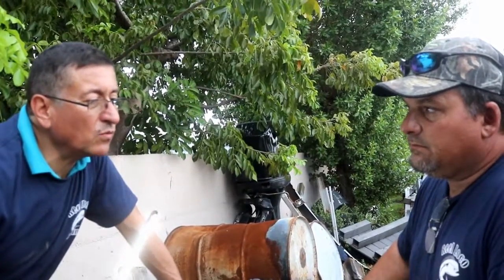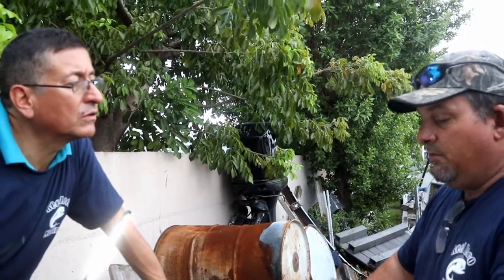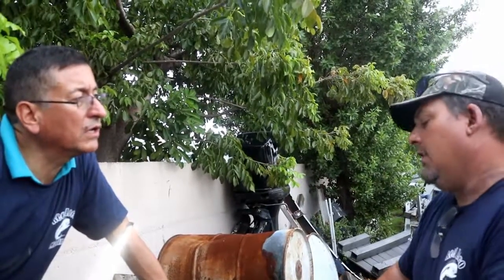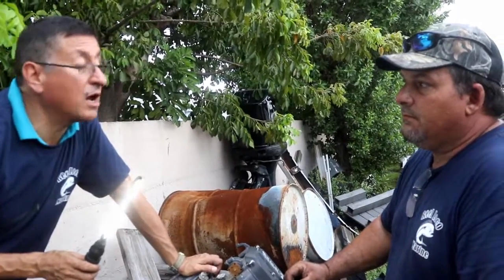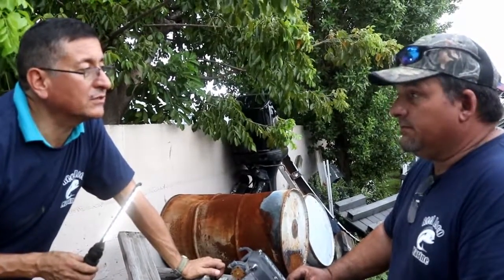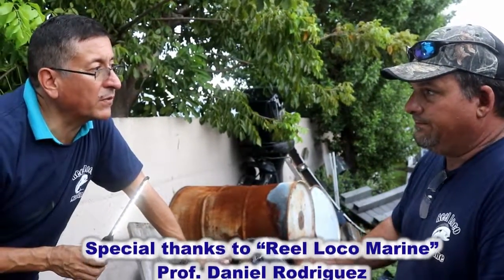And what is the symptom when the timing is a little out? Well, you'll have a sneezing. Basically, when the engine is running, all of a sudden it'll start sneezing on you. It's running lean. And if it's running rich, obviously it's going to... Or in some cases it's a hard start. Absolutely, hard start. That's the most common. And you won't get full throttle advance if the timing's off. Okay, perfect. Thank you.